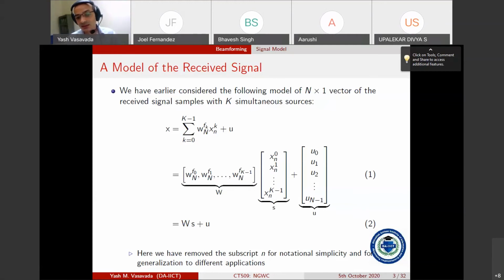And so that is where the synchronicity comes into play. Whether we can assume that the QPSK symbol X0 transmitted by the first transmitter has been synchronously received with, let's say, 8 PSK symbol X1 transmitted by the second transmitter. Whenever that is applicable, we can write the same equation number 2. When the synchronicity is not there, then we have to be a little more careful. We can still come up with some equation like equation 2, but it becomes more complicated.